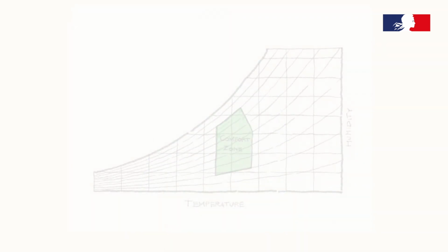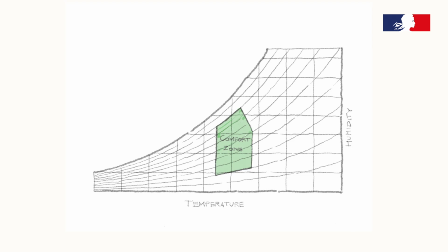Natural ventilation is an ancient way of free cooling. It is the use of prevailing wind to achieve 2 objectives: to remove the heat generated inside our buildings and to make people feel cooler by circulating air at a certain minimum speed. Theoretically, natural ventilation widens the thermal comfort zone with the increased air velocity. The maximum cooling effect is approximately 5 degrees Celsius.